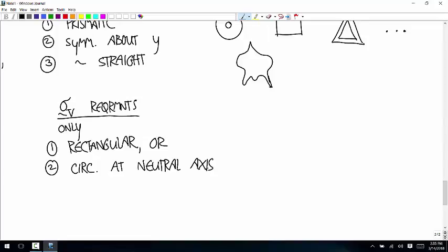Why would we even care if we can do it just at this one location on the cross section? That at least has the usefulness of being where you have the maximum shear stress due to shear force. But that doesn't mean that when you calculate all the stresses, that's where you're going to have the maximum shear stress that you find by doing the principal stresses and stuff.